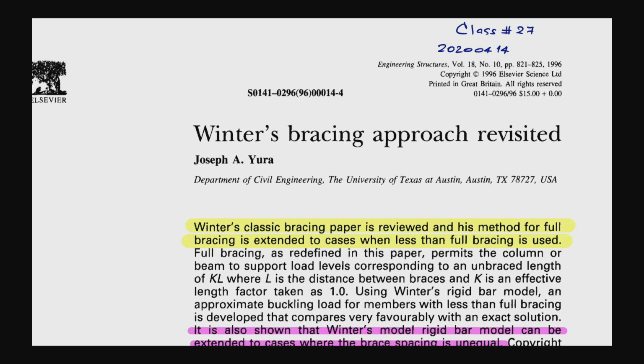And in reality, the ideal stiffness and ideal bracing force are not actually enough for reality, because these two ideal things assume that the column of our interest has to be perfectly straight. But again, in reality, the column is not perfectly straight, and the initial out-of-straightness, the initial bow, will cause us the secondary moment, and that will bring the column to buckling earlier than the ideal column.